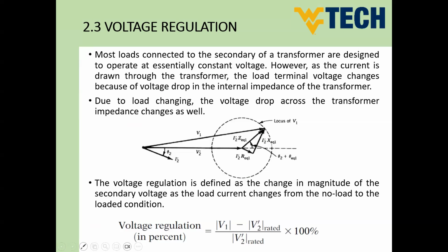For static loads, it's completely opposite. You know that power, guys, is proportional to VI power factor. So in case of dynamic loads, power should be constant, which means if V decreased, current will be increased. And for sure, the current increase may burn a lot of things, maybe burning the cables, maybe burning the load itself. So it's very dangerous. So we should make sizing for our transformer to provide constant output volt.